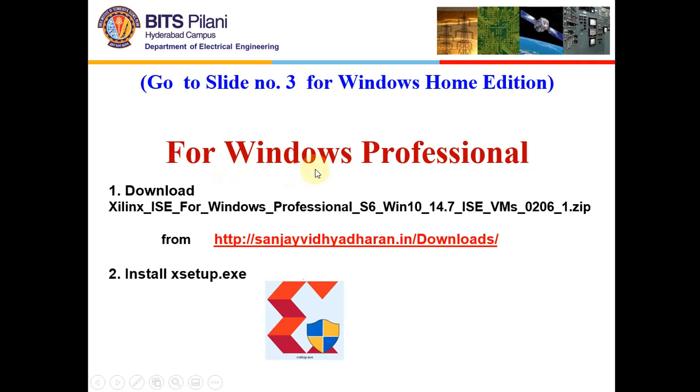Those who have got Windows Professional, you can go to this link and download the installation files for Xilinx. Okay, once you unzip that folder, you will find xsetup.exe. You just run it, so it will install a virtual machine, and you will get a small shortcut named ISE. Okay, so you got to trigger that ISE to get into Xilinx.